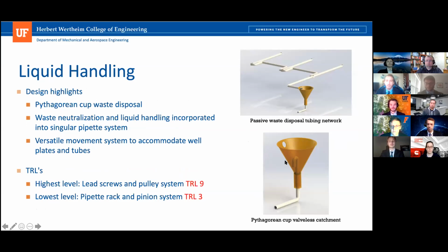We came up with this simple design, basically just an off-the-shelf funnel that you can buy at pretty much any hardware store, and we use PVC piping. The way this works is you can see the bend that comes up through the funnel. You would start with an initial level of fluid in there that is above the lower part of that bend so that gas isn't escaping.